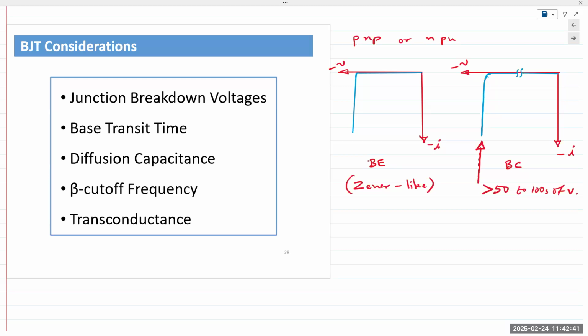Yeah. So continuing from that point. The charge carriers coming from the emitter into the base are injected into the base. So now the base stores the charge. And then when you have the reverse bias, they are pulled into the collector. The amount of time it takes for these charge carriers to transit through the base and through to the collector is known as the base transit time.